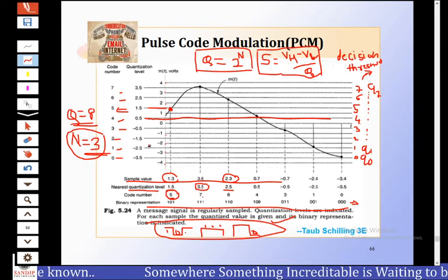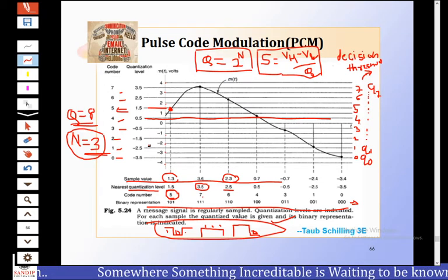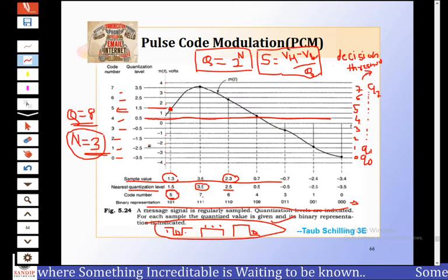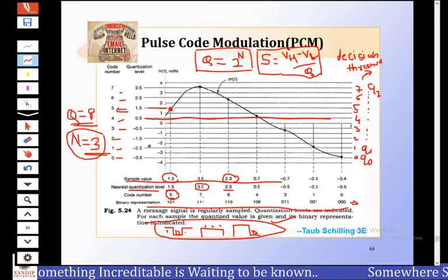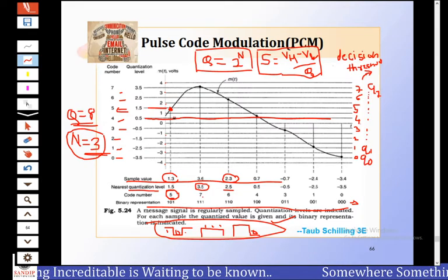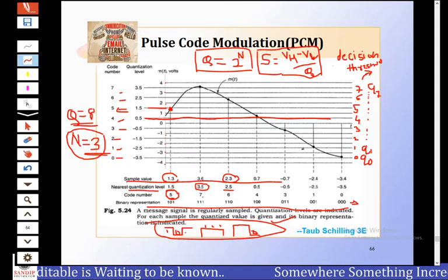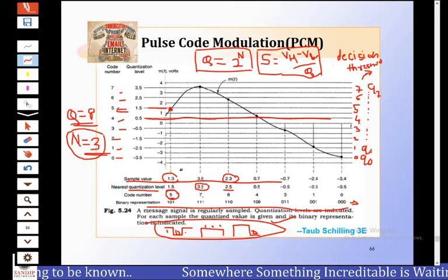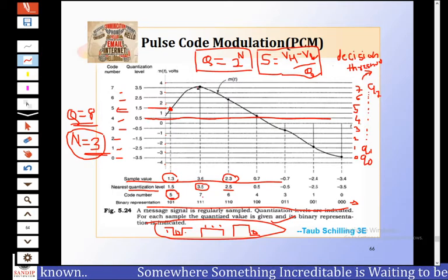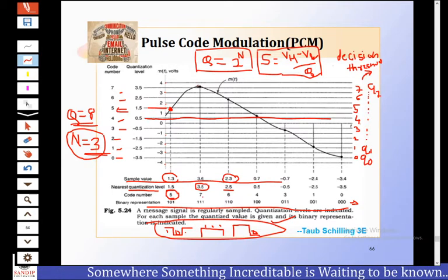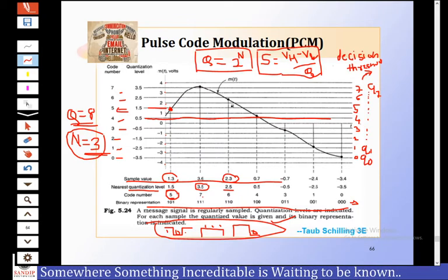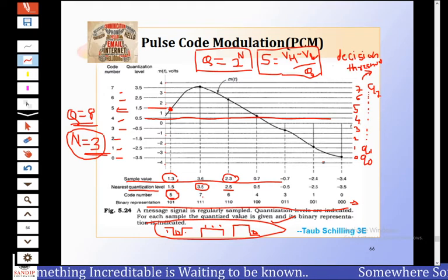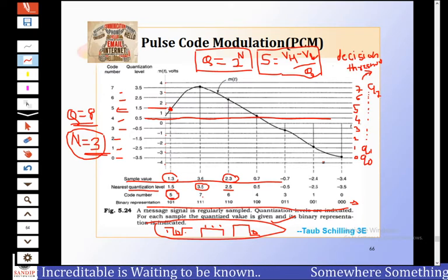Now we are going into the details of the quantization process. So what is meant by quantization? Before that, we explained that quantization is nothing but approximation. How exactly it is done, we will understand here. Now consider this is the analog signal. Let us consider its peak to peak voltage level is plus or minus 4, that is, plus 4 to -4. So this analog signal, after sampling, is divided into a number of stages, number of levels.